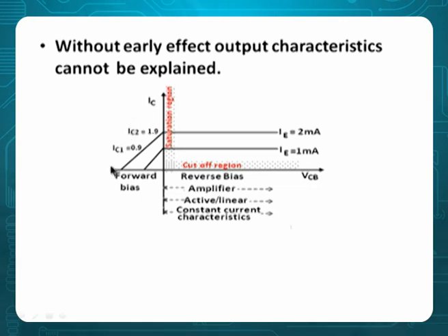Therefore, if you draw the characteristics, what happens is here. And the very interesting, surprising thing is, the characteristic starts right even on the negative side. Most people start from the supply here. They suddenly see a large current coming and maintaining constant. They don't see this portion of the curve. You know why? Because they are straight away giving a positive output voltage. My suggestion is, for some time give minus values to the output, then slowly it will rise, then you give positive. Normally nobody does it, that's why they don't see this portion of the curve. But if anybody is interested to see this portion of the curve, they should go from negative supply at the output, increase it to 0, that's actually saturation, then it starts active.